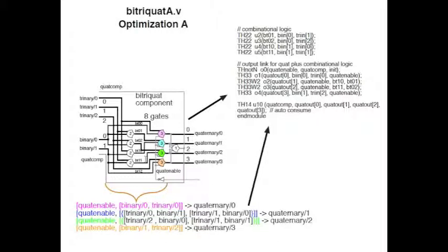So it turns out we can optimize the combinational logic into the enable rank of a link, but not past the enable rank into the completeness logic. And to represent that symbolically, we will AND the quad enable into each of the equations, integrating the enable rank into the equations themselves. Now we can optimize these equations simply by refactoring the equations.